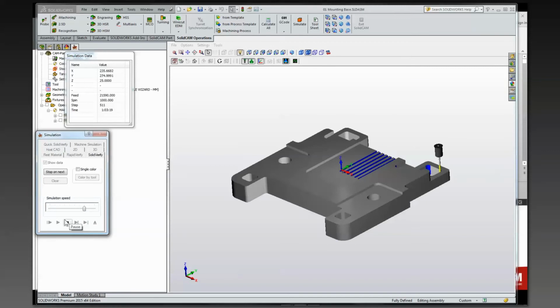we've got the remainder of the pockets machined out in here. Now, what's really nice about this is you notice that all those little slots that the previous operation couldn't pick up, we didn't have to create a separate geometry for it. It was in the original geometry of the pocket recognition, and the rest material picked everything up and machined it out just like it was a regular pocket. Okay, so very clean way of approaching this and very, very quick.